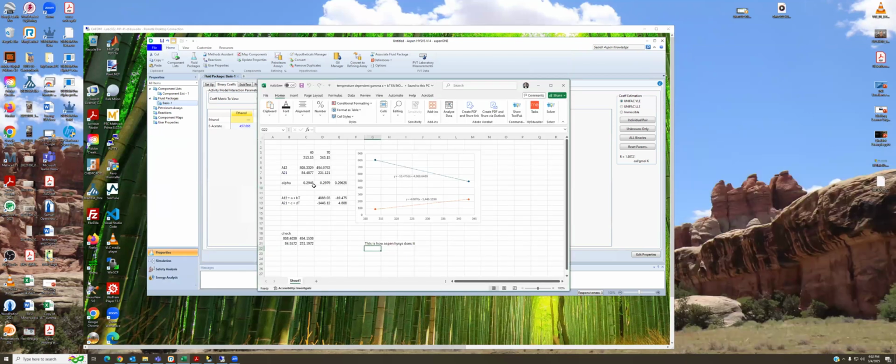So I've taken those parameters from the two data sets that we discussed, 40 and 70 degrees C data. Here are those temperatures in Kelvin. And here are the parameters that you read off of those data pages: A12 and A21 for 40 degrees C, and A12 and A21 for 70 degrees C. The alpha parameter, also important in the NRTL model, has a slightly different value for these two sets of data, and we will assume that an average between them is a sufficiently accurate representation of the data.